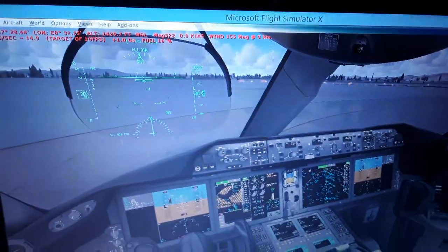So you will see. Also, we have the terrain map with the airports where they are located, the navigation aids, the navaids. So we have the VORs, ADFs, and NDBs, the waypoints which are horizontal and vertical navigation fixes, and altitude and airspeed constraints. You're going to see we have to fly through some waypoints during this or any flight when we create the flight plan. You can see also other aircraft that fly around our own aircraft using the transponder, the ADS-B and ADC.